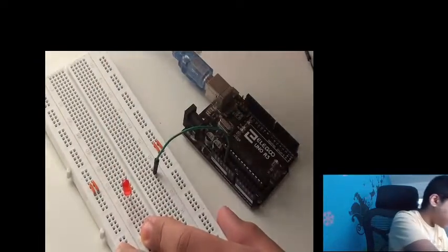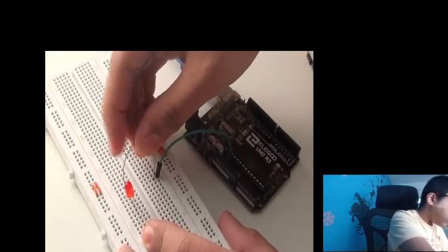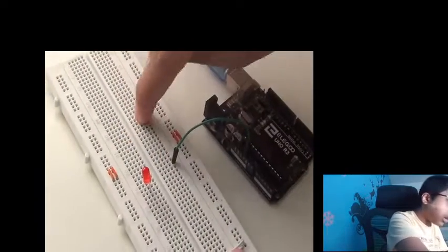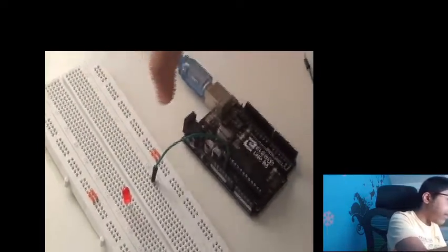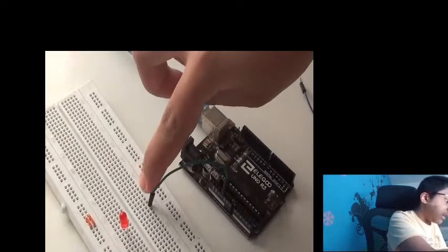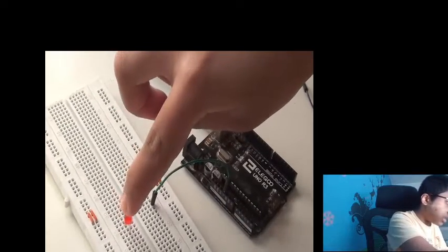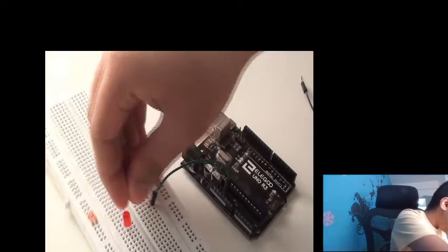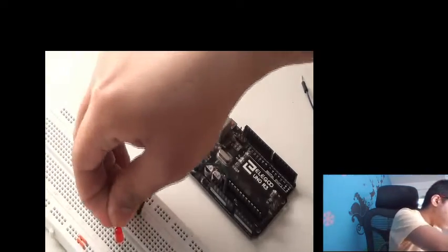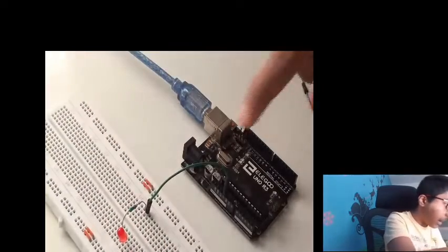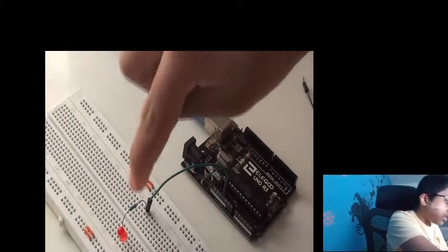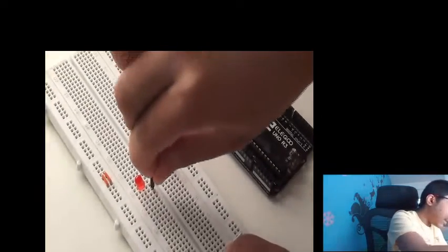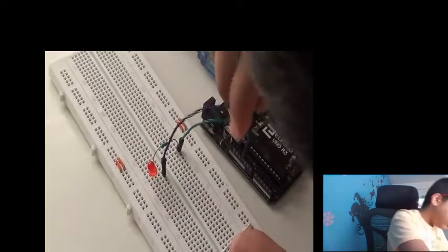So what we're going to do is put in a resistor. Now note that there's this bridge and pins on either side of the bridge are not connected. So if I send a signal over here, right, the LED is not going to turn on just yet. So I need to connect it through a resistor, right? Now current is going to flow from the 5 volt pin. We are directly giving it power, right, through the resistor to the LED. Finally, we are going to send that to the negative terminal or the ground, right?